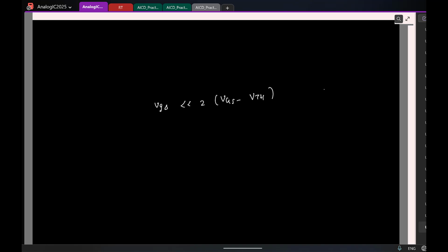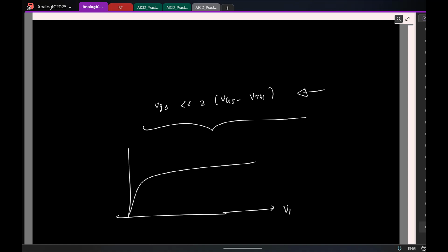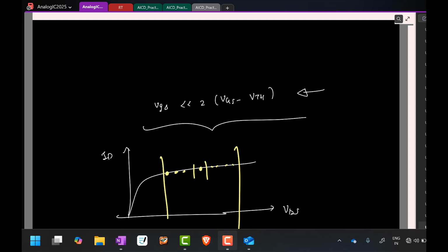But at least we want to make sure that the transistor is in saturation, right? So this is a much stricter limit, but you don't want to give very strict limits on the end application. As long as your transistor is in saturation, it is going to reasonably work, right? Because finally I want to bias my transistor in this range of VDS and ID, that's all. Now around a given operating point, for small signals, maybe I have to swing only so much, correct? But the operating point itself can take any values here, correct? We are specifying that limit. I'll elaborate in the next class if it's not clear. So we'll continue from this point in the next class.